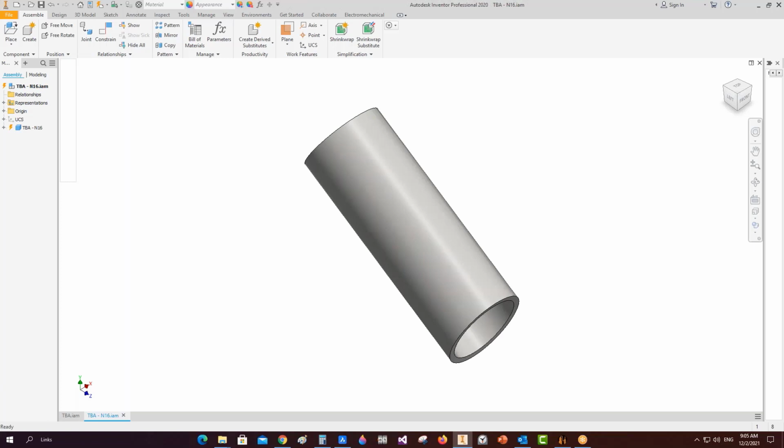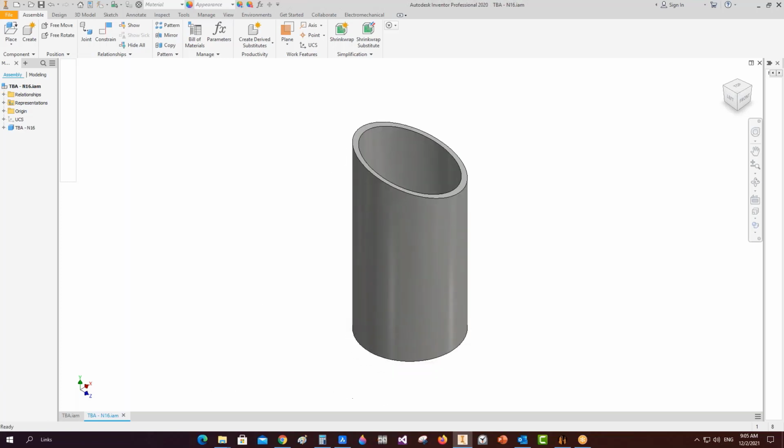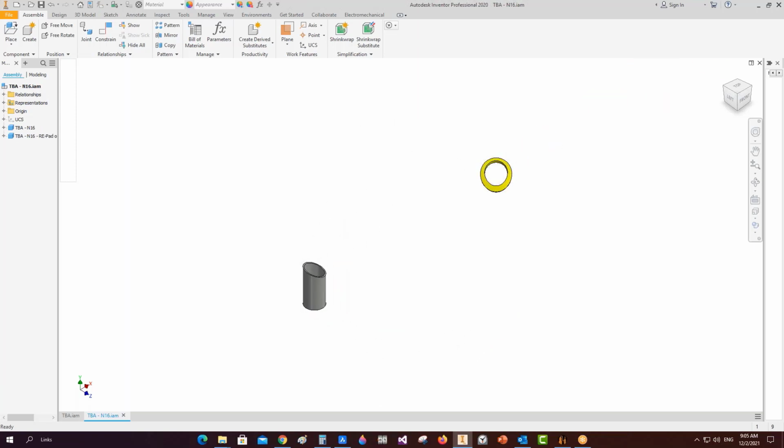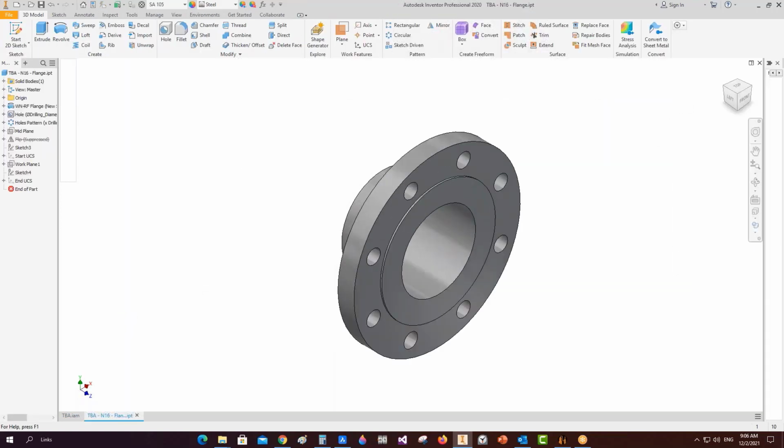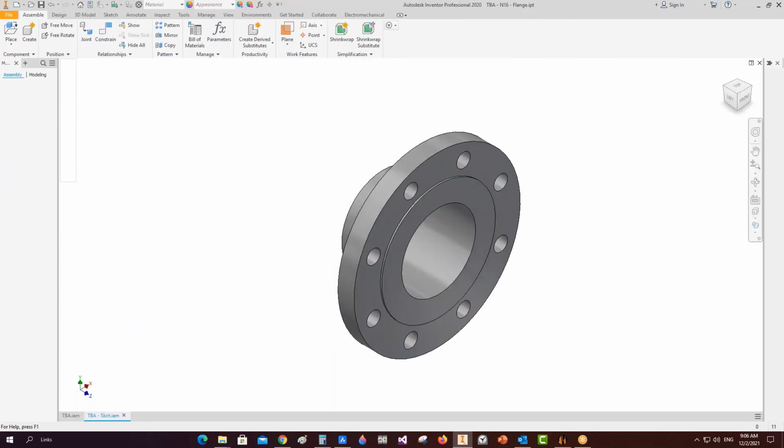Here on this nozzle, actually it should be with an elbow. The bottom nozzle on the head may need an elbow which will exit from the skirt. As mentioned, there is no information about this elbow in the Access database file, so SEG will detect it as a radial nozzle without an elbow, connected to a flange directly.